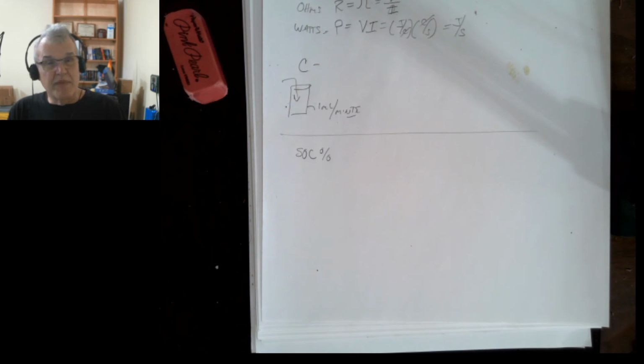or so, 95%. My batteries, again, these LG 26 batteries are rated for 2.6 amp hours, and capacity testing them, I have most all of them, 100% of them, between 2.598 amp hours and 2.8 amp hours. Some of them go a little bit higher than that. I think that's more a function of the capacity checker than it is the actual battery. But basically, they're all in there at 2.6 amp hours. So they're all pretty much at 100% of their capacity, which is what you would want.